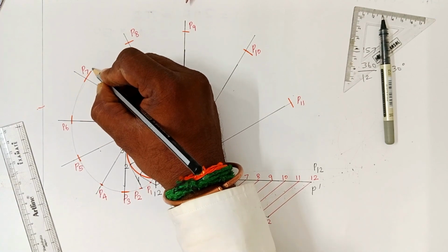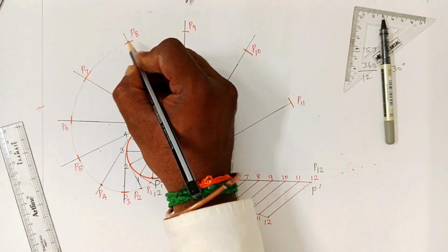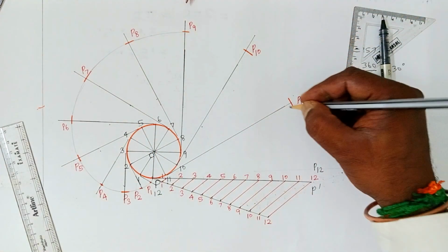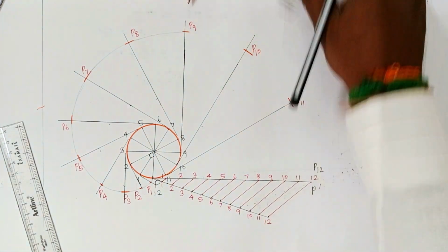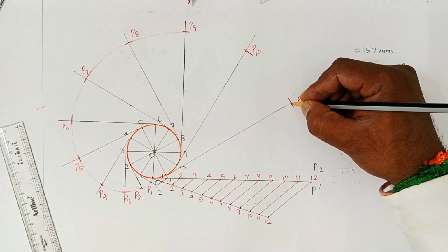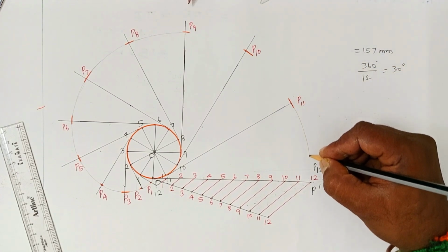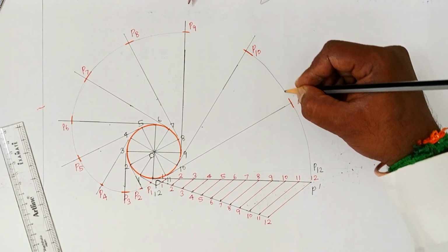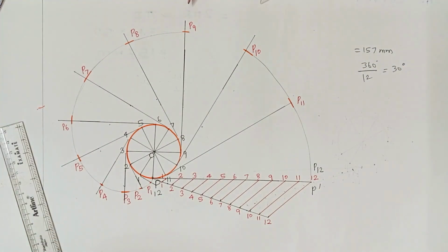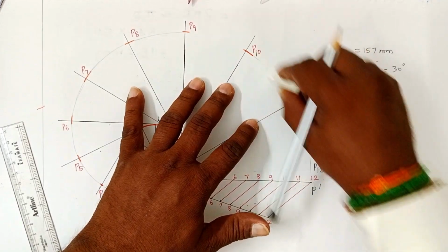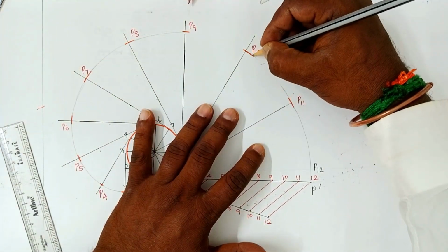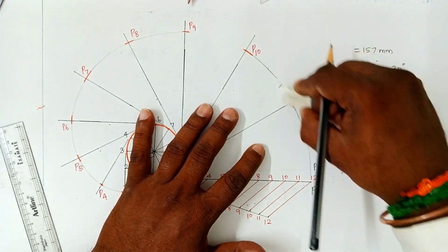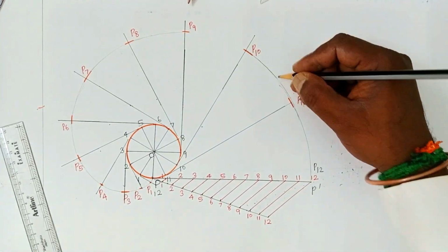First you draw a lighter smooth curve. Don't turn your drawing sheet or drawing board. Your hand should bend. If it goes wrong, you can erase that part and correct it. Waviness is not accepted. It should be a smooth, gradual curve. Painting is not accepted. You don't paint like this.